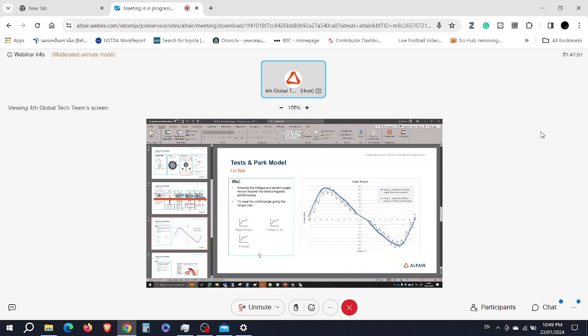Let me just say something here. If you impose, you have the initial position of the rotor, and you write your current according to IDIQ, then if you vary the control angle, you will plot this static curve, right?